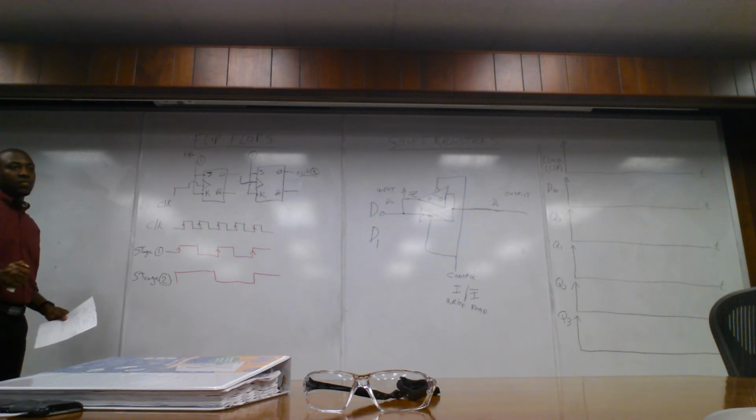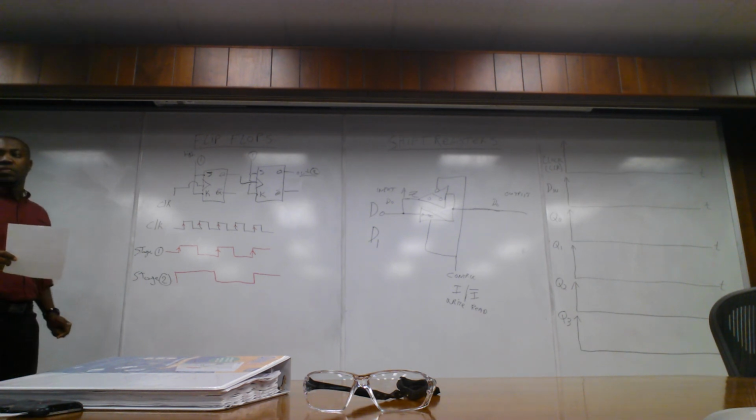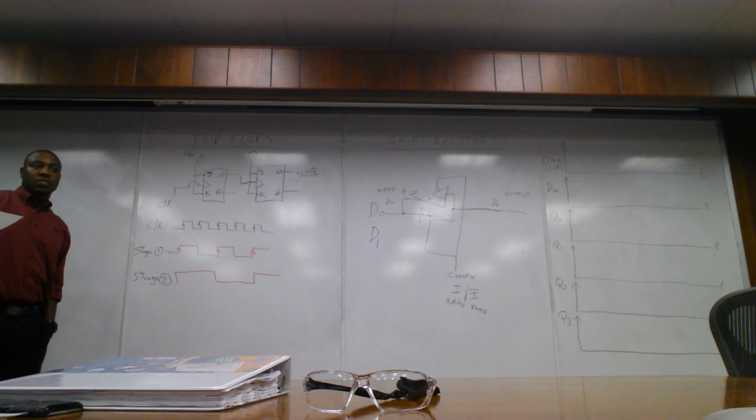Practically, how's that used? Well, in this microprocessor system here, I put a chip in there that only runs at a maximum clock frequency of 4 megahertz. But I had a crystal of 12 megahertz. So what I did is I divided down 3 times, to get that operating frequency for that microprocessor.